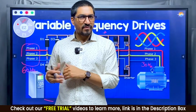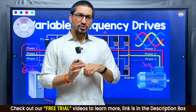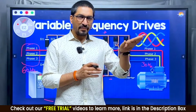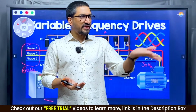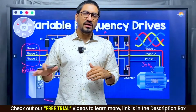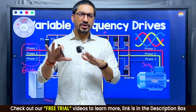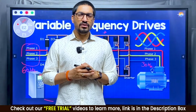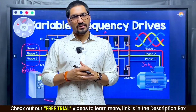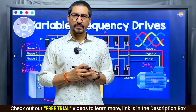So if you increase the RPM of the positive displacement pump, the feed rate of the sludge to be burned will increase, and when the temperature was falling, it will again start to rise. And vice versa, if the temperature is increasing too much, you need to reduce the RPM of the pump. That means using a VFD, you are controlling the speed of this motor, which is connected to the feed pump of the sludge, feeding the sludge into the burner of the incinerator.